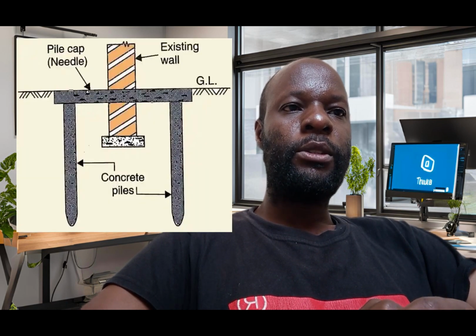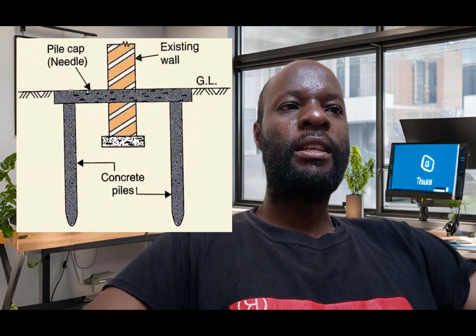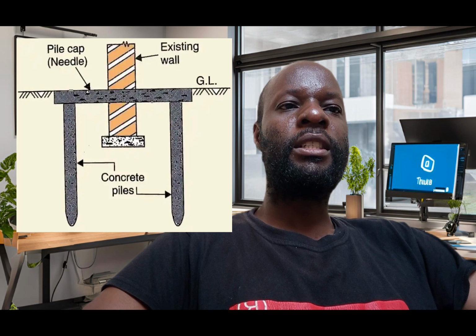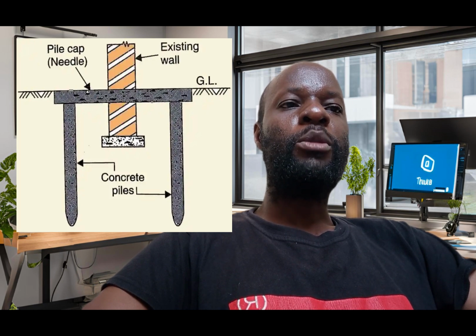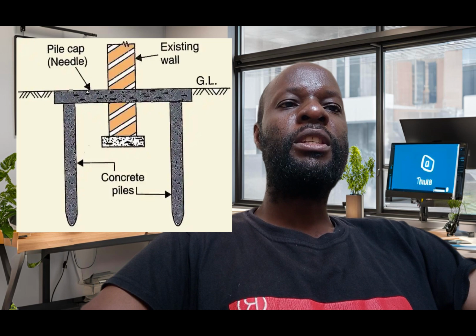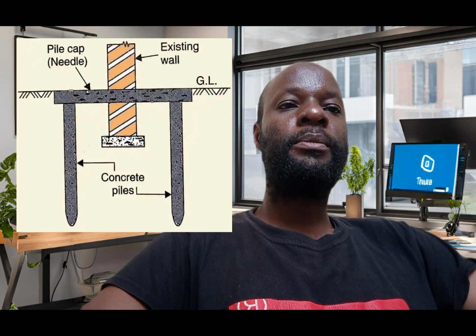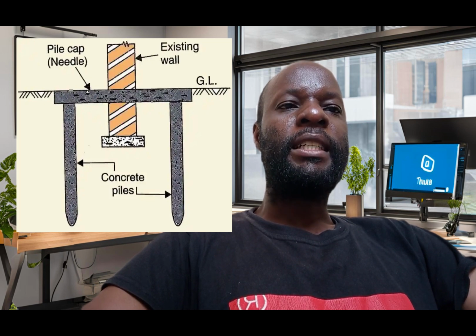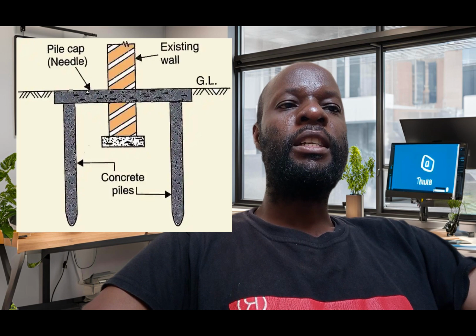And then we have the pile underpinning method. In some circumstances, such as those involving swampy areas, severe loads on already existing structures, and loads that need to be shifted to a deeper depth, the pit approach may not be feasible or cost effective. So using a pile technique might be used in these instances.